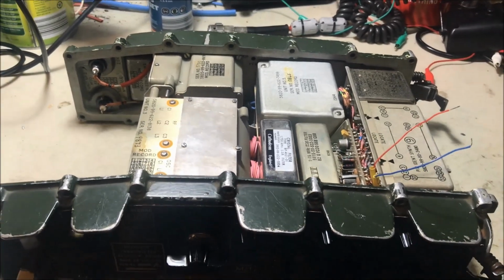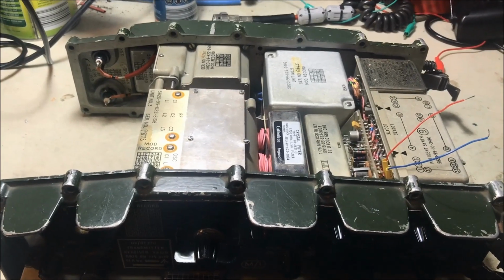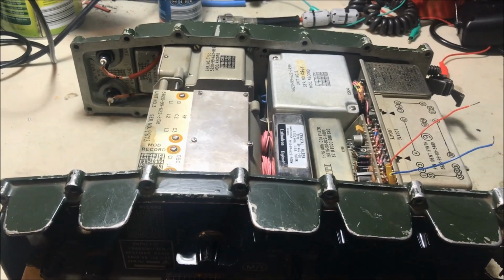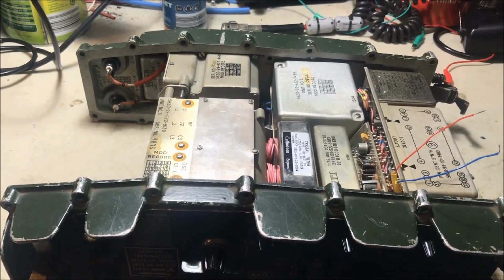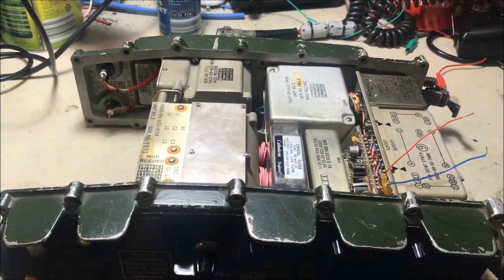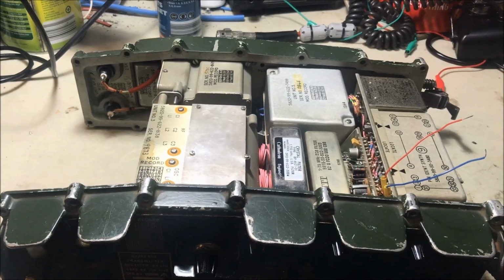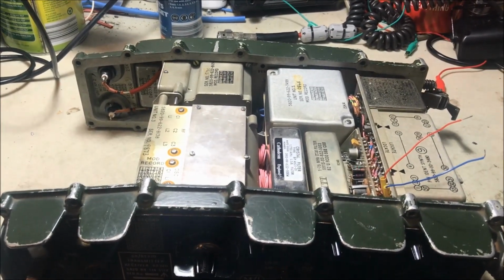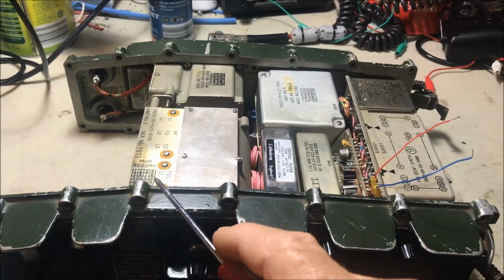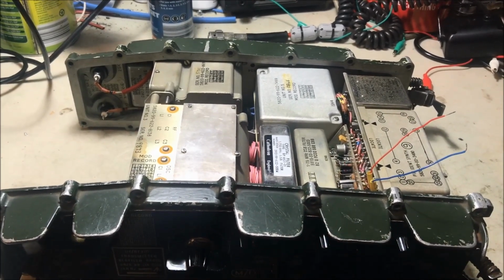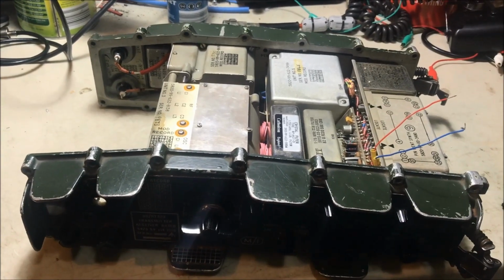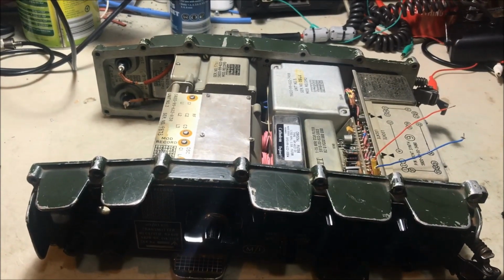Normally this set would be dead. This would now become a spare set. I'd use it for bits and pieces for my other Clansmans, pass the parts on to other people, etc. But there's been some developments, and if you check out my video on YouTube titled Clansman 320D DDS VFO conversion, I've got the option to remove the synthesizer and the 3H board out of this set and replace it with a digital DDS VFO and turn it into a digital front-end tuning Clansman 320D.